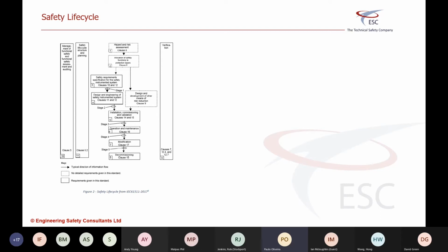As you allocate that safety function as a protective layer, you are effectively saying, I need to know now what that safety function needs to do. So you need to specify it. And the specification has very little in terms of risk target type of figures, apart from this is what we think we need, this is what we think we will get.